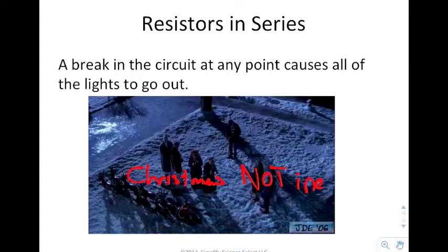The reason for that is if you had Christmas lights, and there's 100 of them on the string, if one of those things went out, they would all go out. Well, if they all go out, how are you going to figure out which bulb it is? So you'd have to test every single one. Because of that, you have bunches of wires that are used for these bulbs, and they're actually connected in parallel.